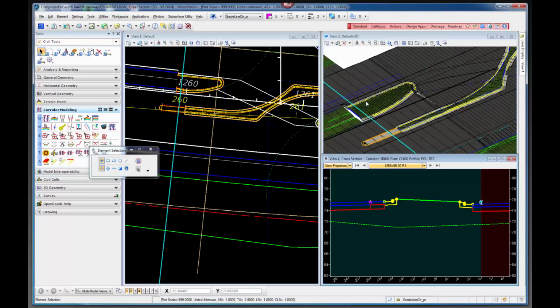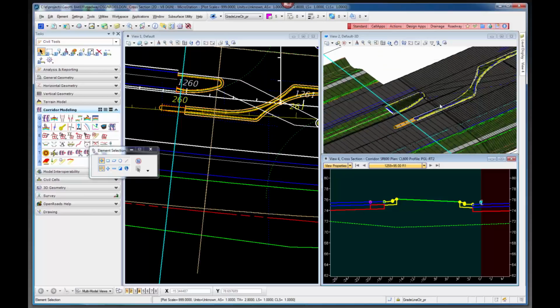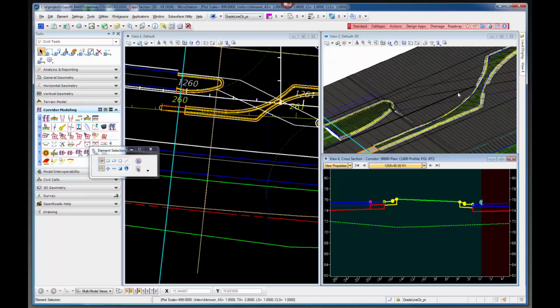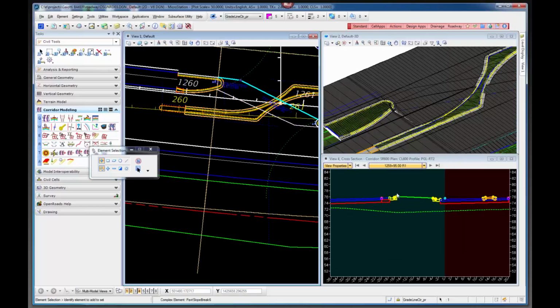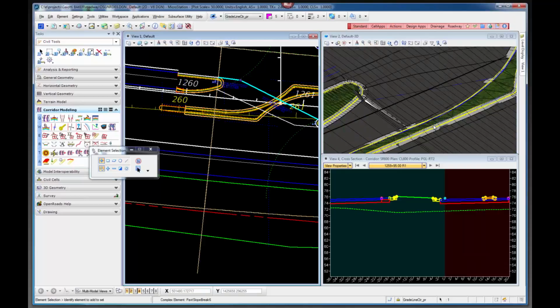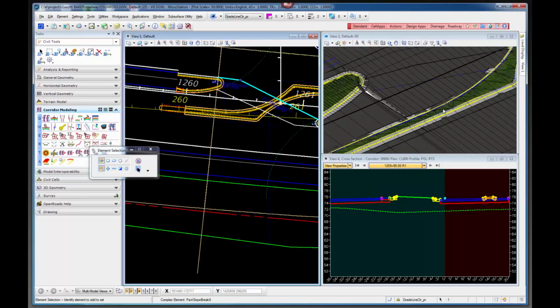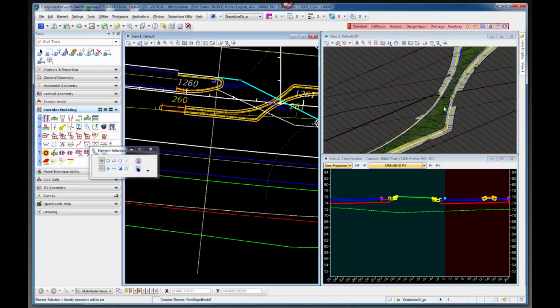This way, part of it is being done with a template and part of it is being done with detail modeling using the crossovers. And then, of course, you'd want to go in and check some of these slopes. This is a location where I inserted these vertexes on these crossover slope lines so that I could get this transition from where the 2% goes up and it's kind of flat across here to the 2% up on the other side. It helped with the breaking of where this transition was in the middle here.